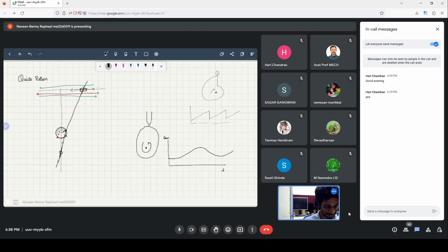It is possible, say you want a very specific kind of speed profile and position profile, to generate the cam from the velocity profile, but when you're doing things like that, you need to study the force analysis also, and it'll be slightly more complicated than that.